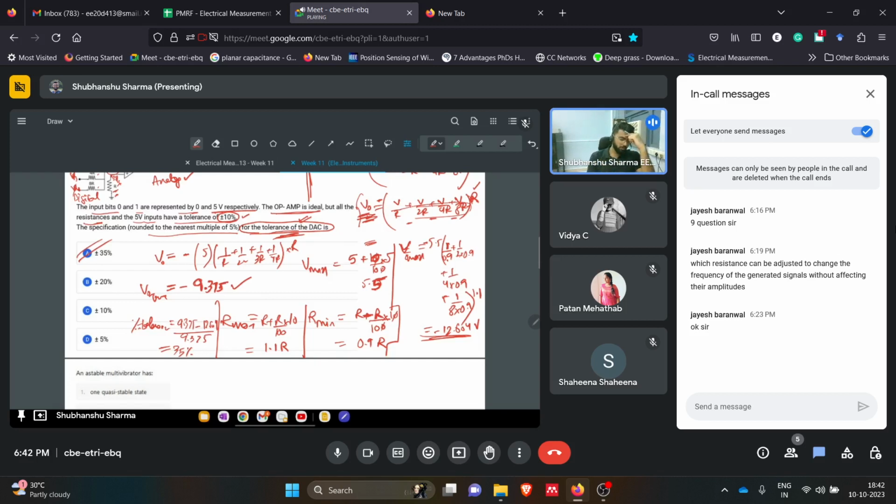So when you are solving these multiplication and division tolerance questions, to find the tolerance of worst case error, you simply add those errors. Let's say there was this power question where you have to find v square by r. So there is a tolerance of r, so you simply add that.